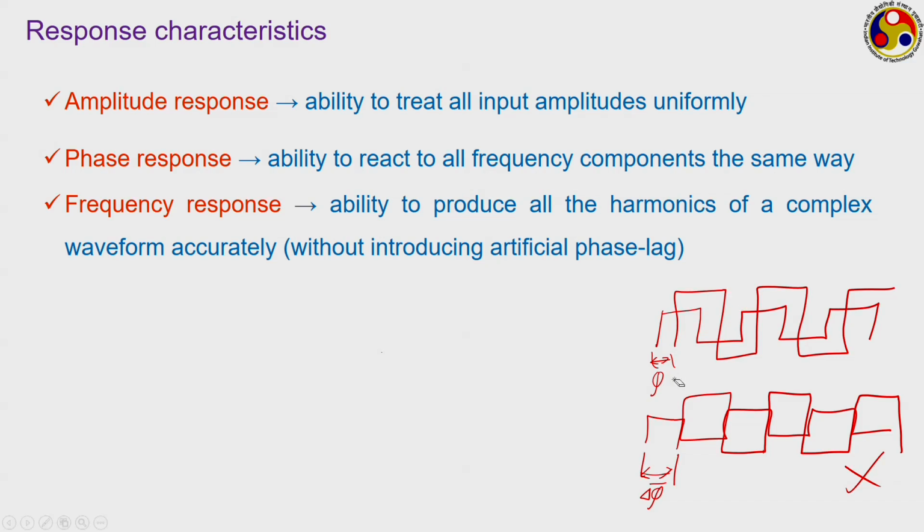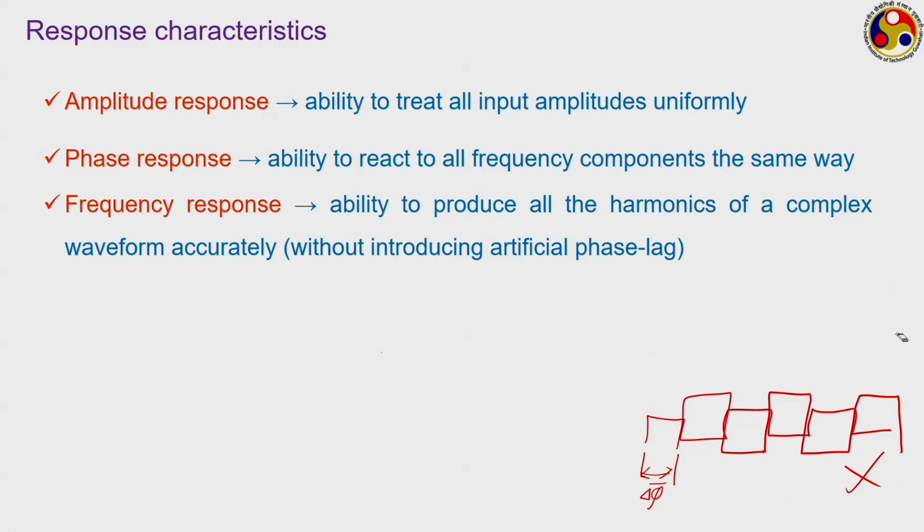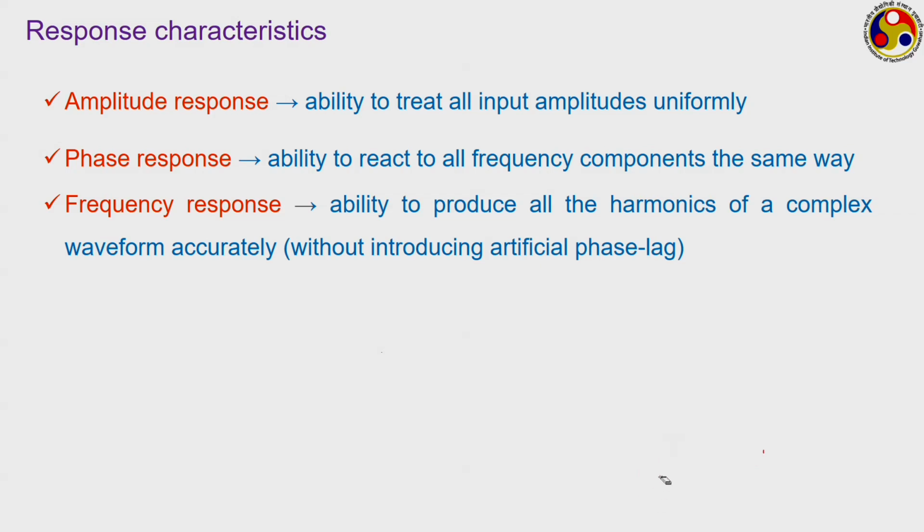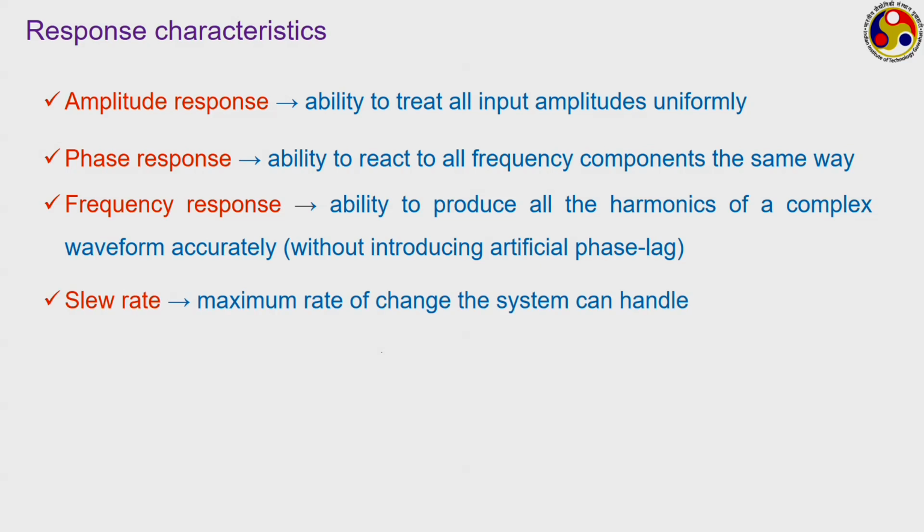This is what we refer to as the frequency response. This is again dependent upon the frequency of the input signals, quite similar to the amplitude response, and we have to be careful about the ranges over which we can preserve the phase lag. The last one is the slew rate. It is the maximum rate of change the system can handle.